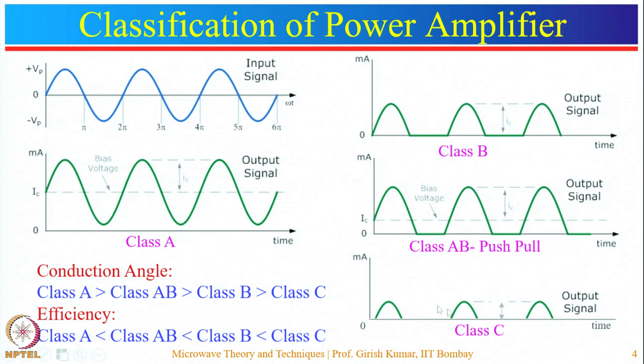output signal. The next type of amplifier is the class C amplifier. In this amplifier, output current flows for only a very small portion of the input signal. So, you can say if you select somewhere here, then the output current will flow only for this region. So, correspondingly you will get the waveform like this. They provide a very small signal with very high output power. So, these pulses are of very high output power. When these pulses are connected with an LC tank circuit, then they provide the carrier wave which is sinusoidal in nature. So, they are used in generating the sinusoidal carrier wave.